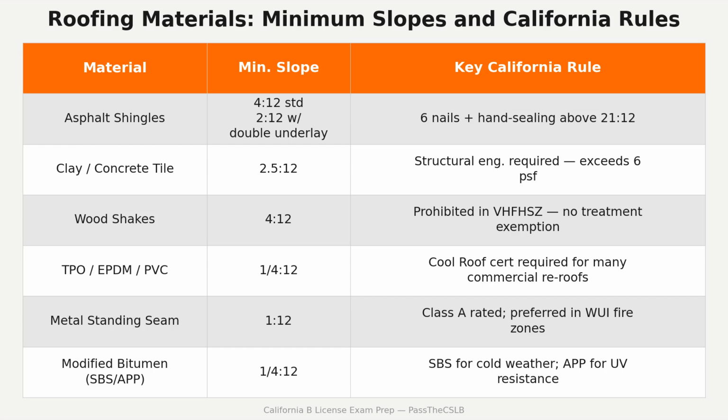The consequence of that compression relationship: the rafters push outward against the exterior walls. Something at the bottom must tie those walls together and resist the outward thrust: ceiling joists or rafter ties. Remove those horizontal ties for a vaulted ceiling without compensating structurally, and the walls spread, the ridge sags. A ridge board carries zero structural load. It is a positioning device.